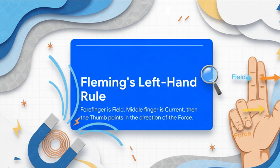Okay, I want you to do this with me. Get your left hand out. Point your forefinger straight out. That's for the F, field. Now point your middle finger out to the side, making an L shape. That's for the C, current. Now look at your thumb. It's pointing up, showing you the direction of the force or the motion. Field, current, force. Got it?